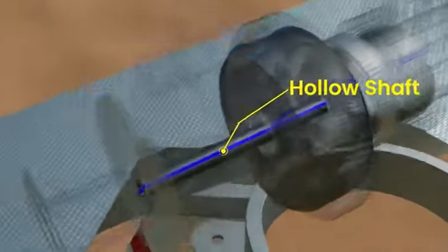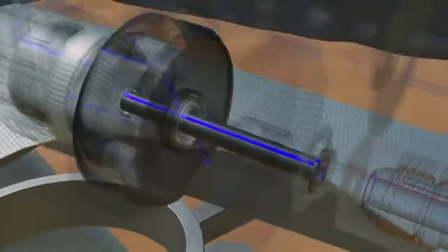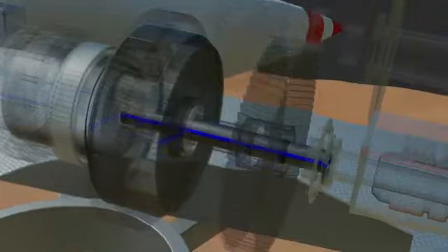In this gearbox design, a hollow shaft extends from the input through to the opposite side of the gearbox. This hollow shaft rotates with the input shaft and has no contact with other gear shafts. Cables from the hollow passage of the main shaft pass through this gearbox hollow shaft, providing a pathway for electrical wiring to reach the other side of the gearbox.